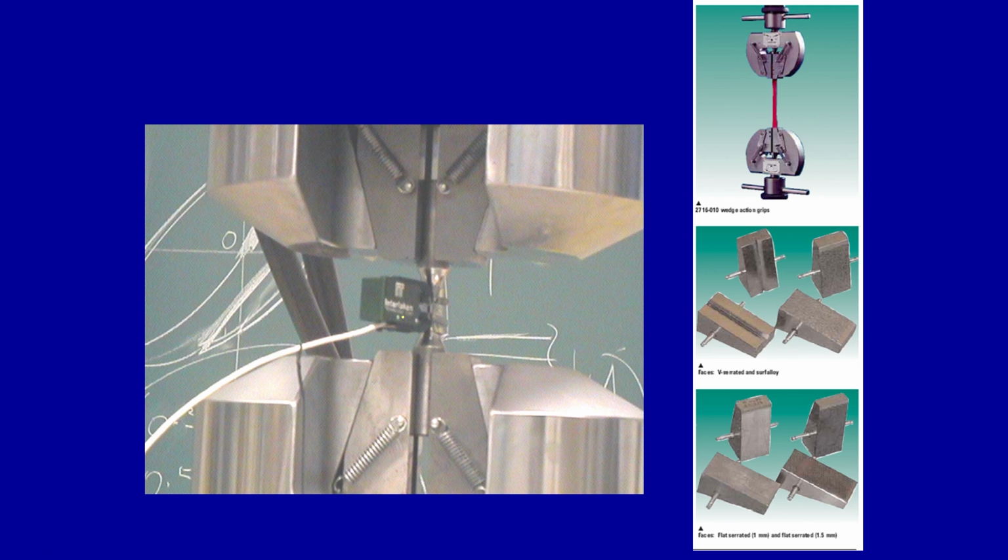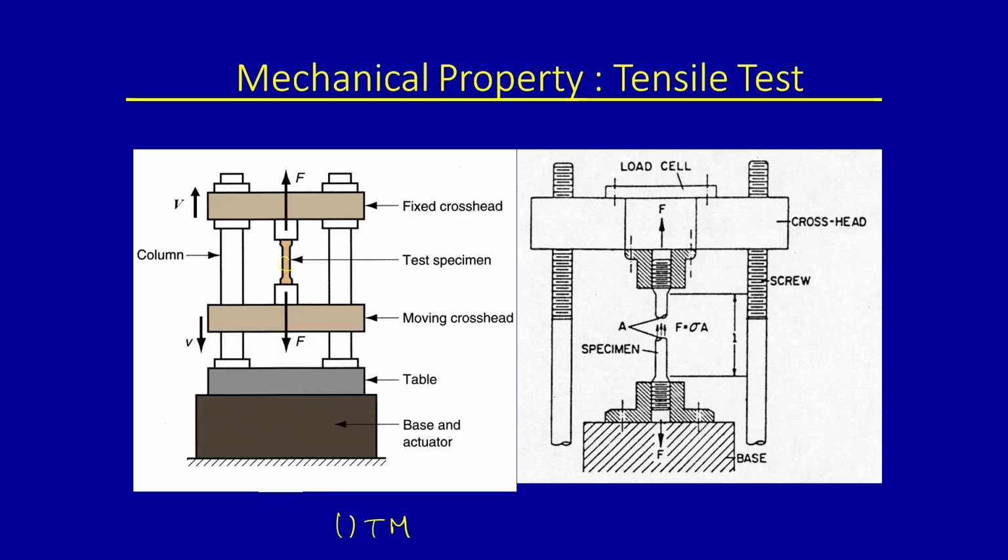So that has to be probed, and that is done by using extensometers. You can see different kinds of geometries are shown. The extensometers are attached to a specific location of the sample, and then we can measure the ductility or the deformation ability of the material.